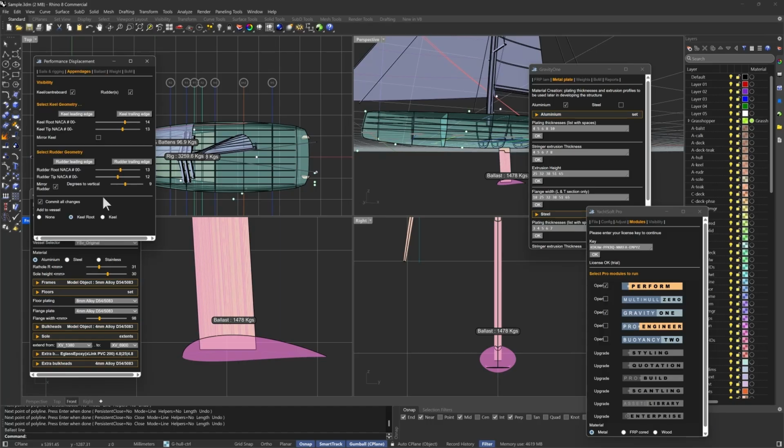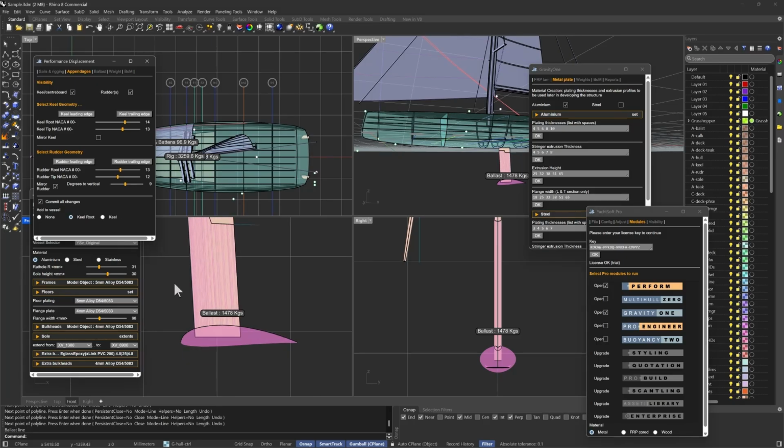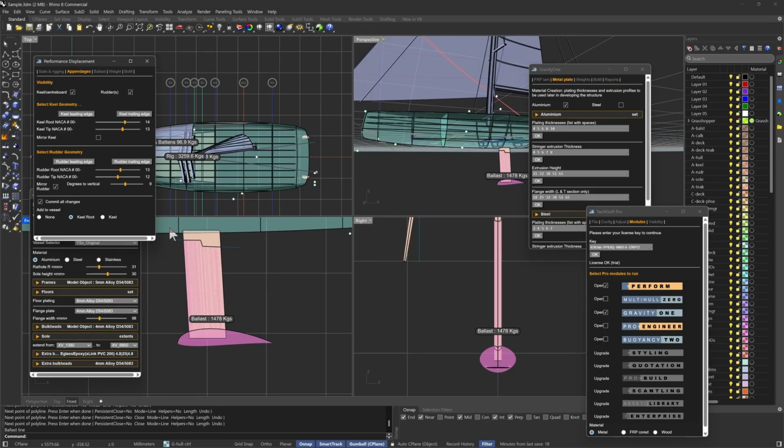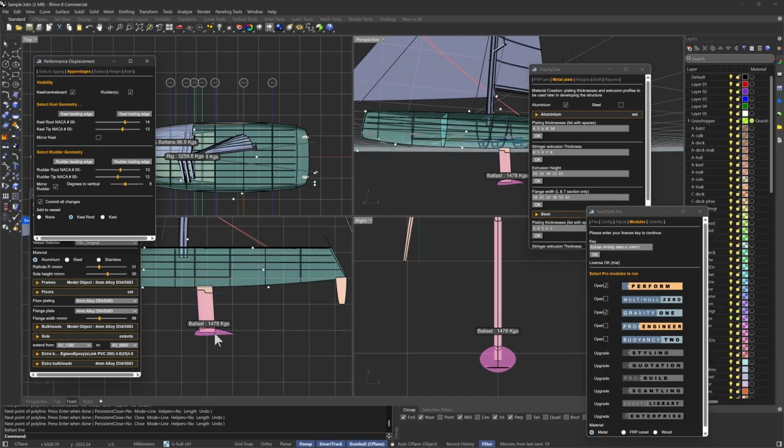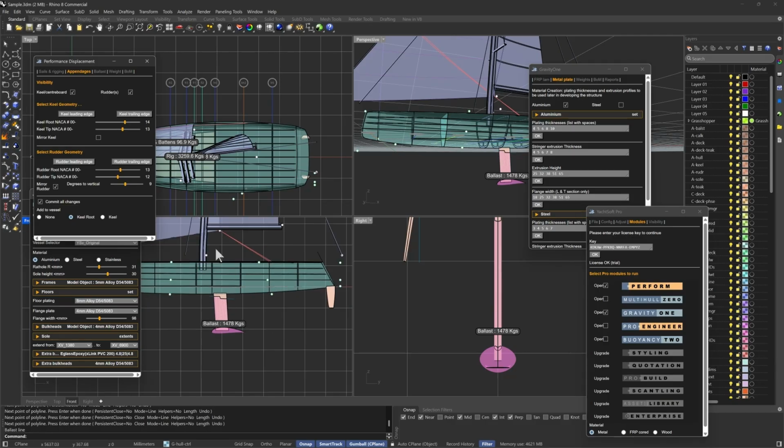I think we've got something on here. So this is going to add the keel root to the vessel, which means that if it's, for instance, in an aluminium boat, this will be part of the vessel, and then this would be the bolt-on piece. If in an infill, say you would add the keel to the boat, and if you have a keel that bolts on flush to the bottom, you would just put none in here. This affects the hydrostatics as well. So now we've got a somewhat weird bulb keel, and let's just do the rig quickly.